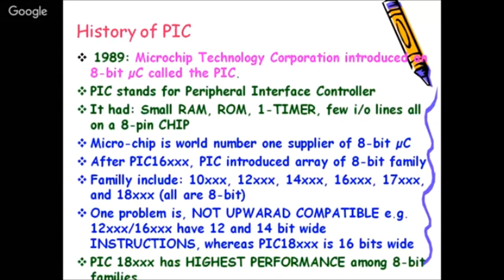So you'll see, when we see that ROM structure where the instructions and the program are stored, the fetching happens 2 bytes wide. So at a time, 2 bytes are fetched from there. So the machine cycle is quicker and faster.